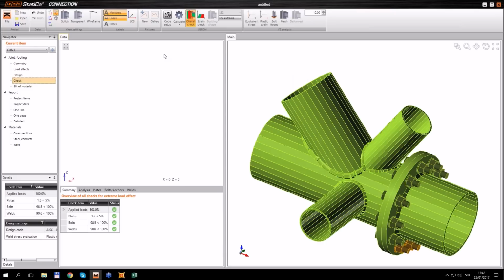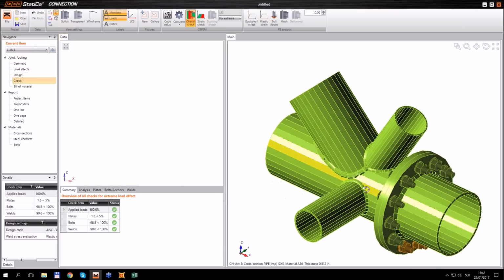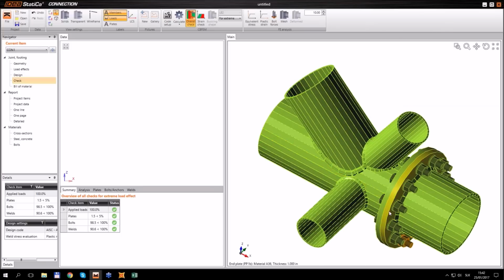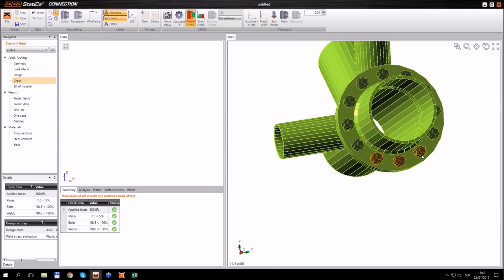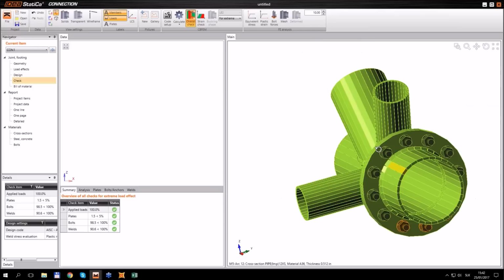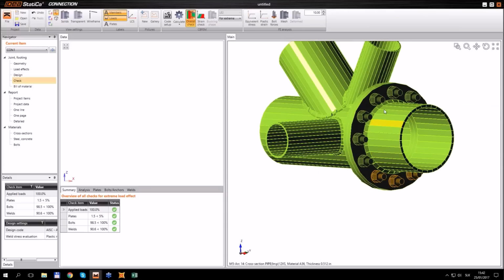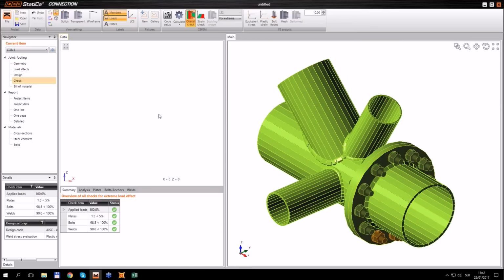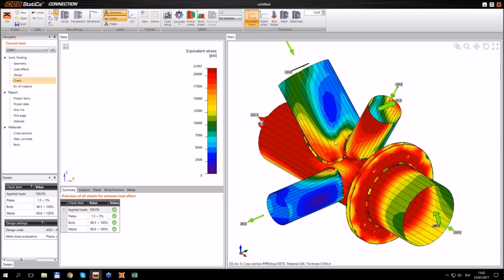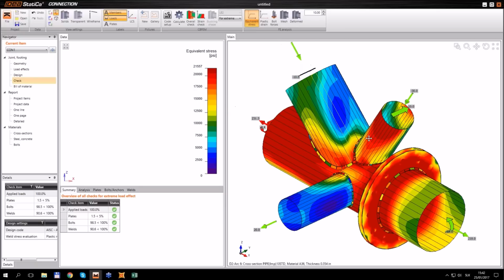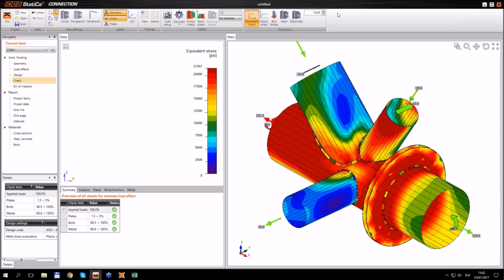Okay, so now you can see on the traffic light that almost everything is in optimal design, and these 3 bolts are utilized between 95 and 100%, so they are orange. I don't want to go into more details about the results as they have been mentioned previously, so if you have more questions, we will answer them in the end.